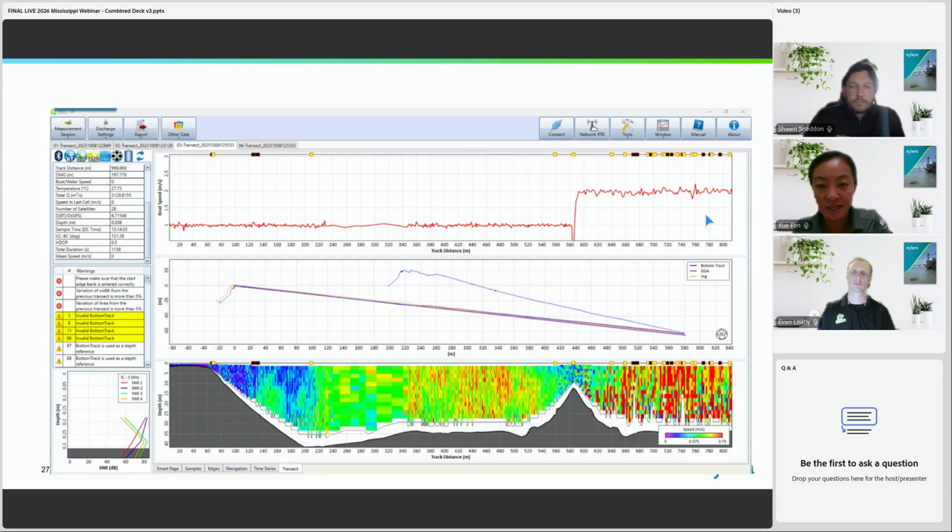So you'll see that for some of this data, we don't have very good data going all the way to the bottom. That's the ADCP struggling with the very fast pace of the boat, as well as bouncing up and down on the surface. That's why it looks very different, and that's why I tossed out this coming-back portion of the transect. That answers the question.